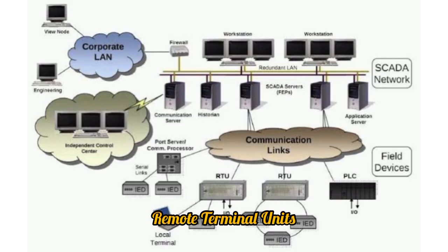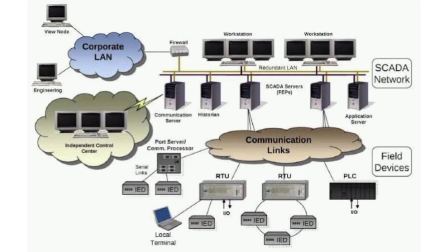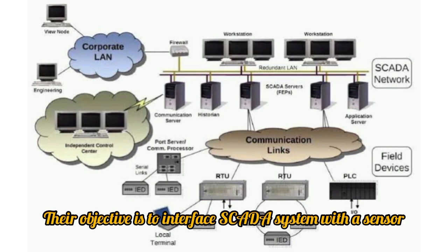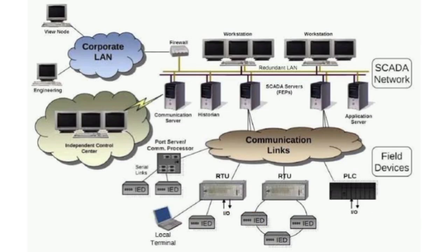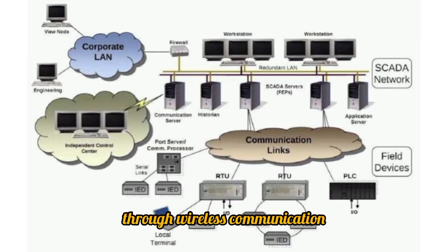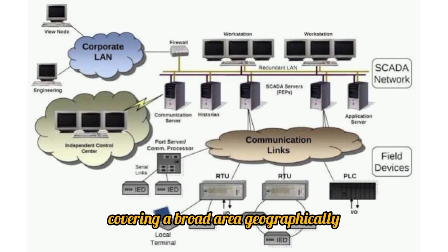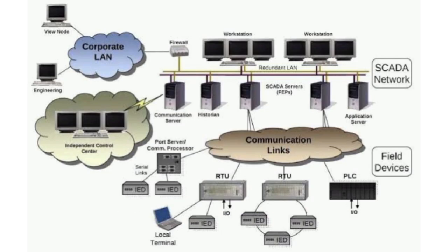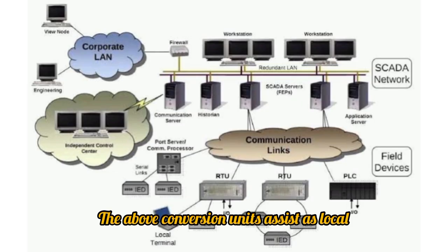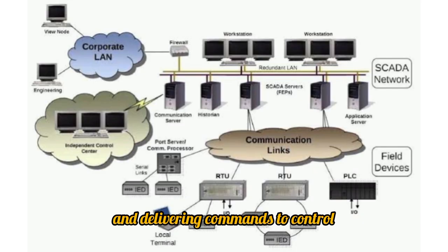Remote Terminal Units, RTU. Remote terminal units are microprocessor-controlled electronic devices. Their objective is to interface the SCADA system with a sensor or whatever objects the RTU is connected to through wireless communication. Therefore, they are considered good for functions covering a broad area geographically. The above conversion units assist as local collection points for gathering information from sensors and delivering commands to control and protection relays.